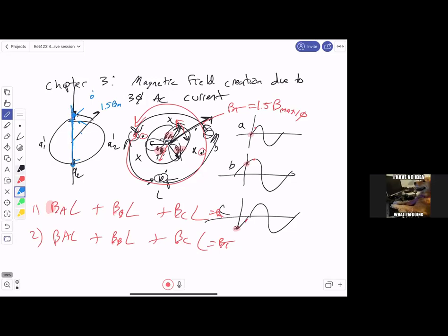So what I've done is electrically, this is going to be the start of my sine wave. I'm going to go up and down, and then start back up at this point right here. This would be the A2 point. This is the A1 point. So as I rotate along, I'm going to get 360 electrical degrees. And why is it 360? Because I've got a complete electrical sine wave, 360 degrees for one sine wave, but I've only actually rotated it 180 mechanical degrees. So to produce 360 electrical degrees, I only have to rotate 180 mechanical degrees.